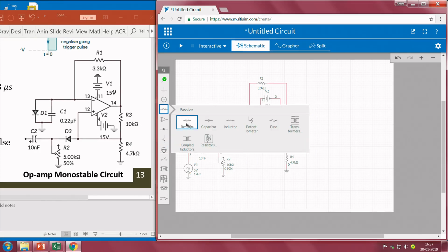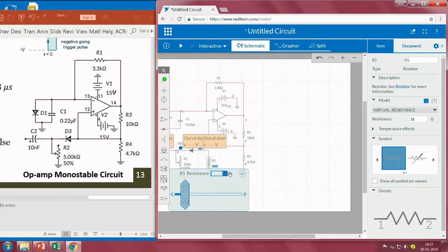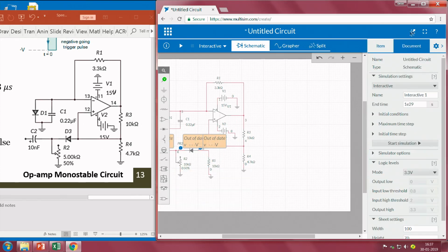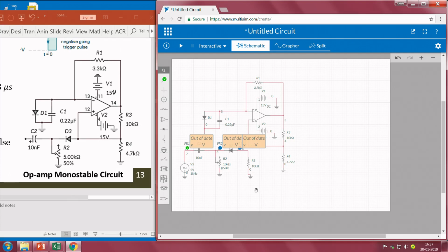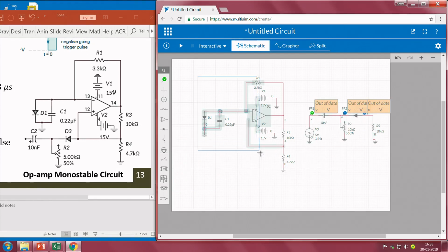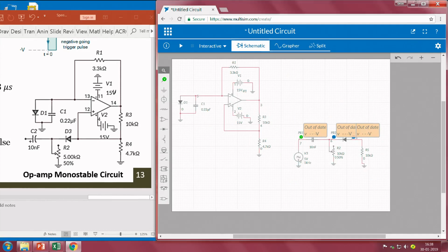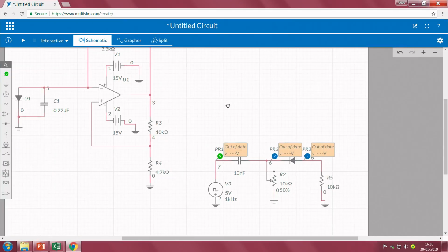So, what I will be taking is one more resistor, but the resistance value should be a little higher, otherwise it may load. It is good to always go with a higher resistance value, so that it will not draw much current. So, it will not load the system too. So, right now the circuit is done. So, I will select this circuit part and keep it aside. Let me select this, then keep it aside. Now, the intention was to check this. Let me check this particular part first, right.